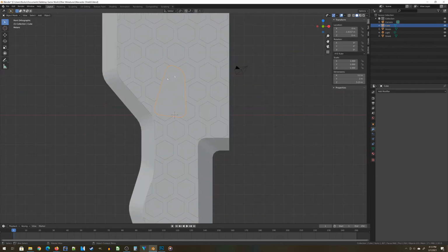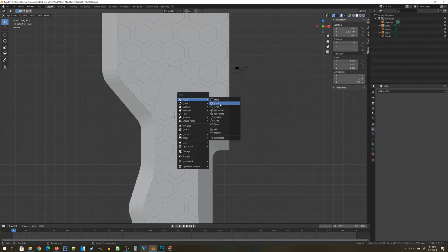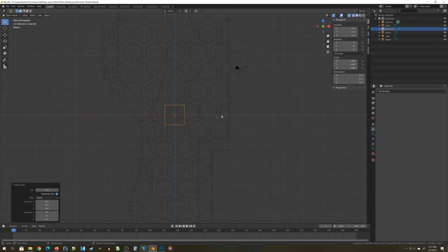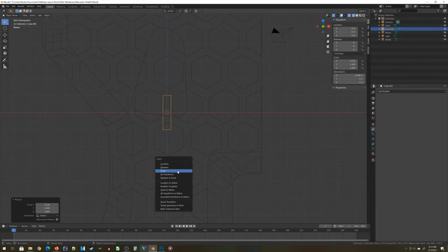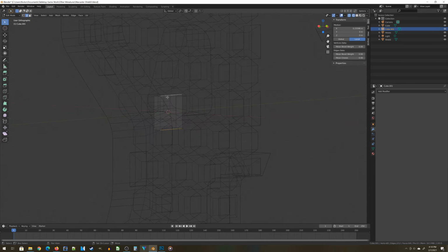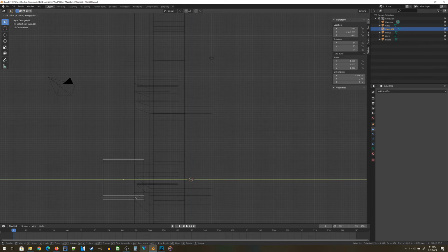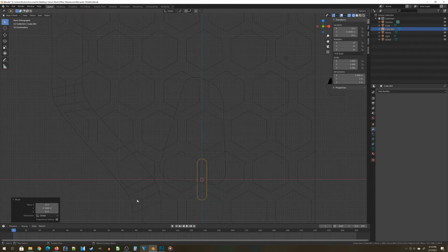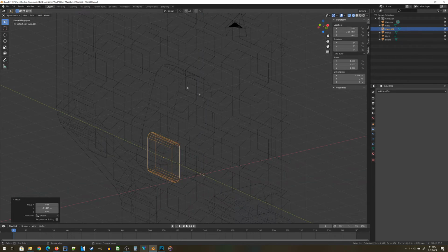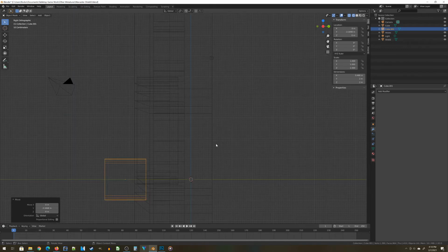But I want to add even some more details into this piece, because I want to cut out a few kind of interesting shapes to it. So we're going to add one more cube. I'm going to take a cube, stretch it out to be a rectangle, bevel the corners, and we'll call that our new piece of detail. And then let me put it so it's kind of like that. So what I'm once again going to do is a Boolean operation. We're going to cut out this piece. So I want to overlap this object with our detail piece in such a way that the overlap is going to be the area that's cut out.